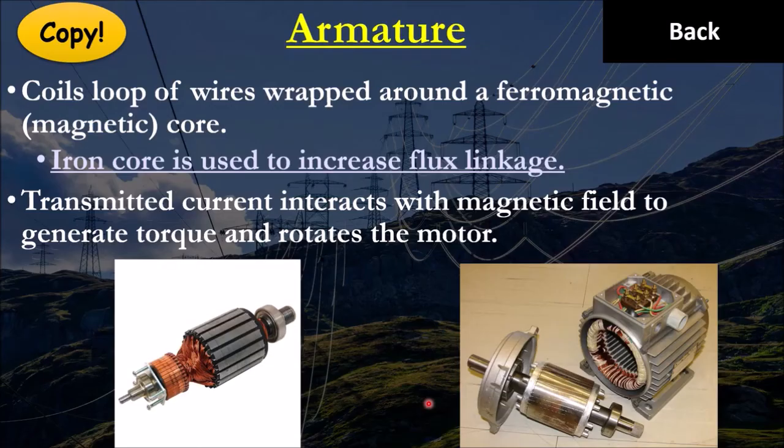So next one we have is the armature, or armature, some people call it. Essentially, this is where you put the loops of coils, so where you want to do your number of turns of coil, copper wire, this is where it is. Usually the wires are wrapped around a ferromagnetic core, so some kind of iron core here.